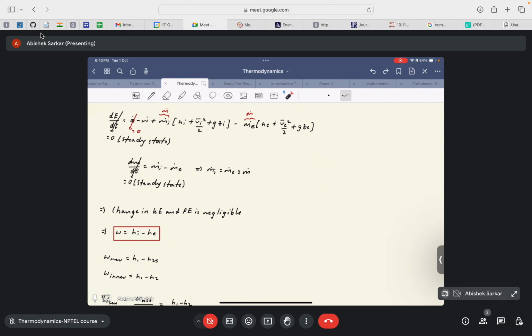Now in reality, there would be irreversibilities in the system because of friction in the turbine shaft, or the change in the temperatures, or because of ineffective insulation. In that case, let us say that instead of achieving point 2s, the steam has expanded from 1 to say point 2. The process is denoted by the red line, which basically denotes an irreversible process.